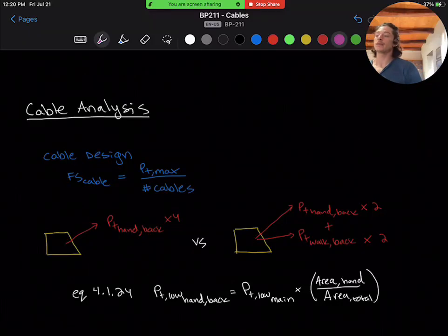Beyond just splitting up the cable forces, how we analyze these forces will depend on the structural system. If you remember from the basic course regarding friction over the tower saddles and walkway humps, we take the more conservative option to analyze our forces. For cable forces, the more conservative option is zero friction, so all of the force is transferred into the backstay